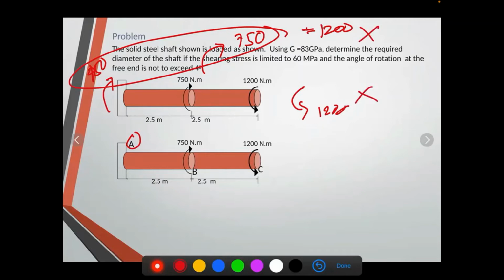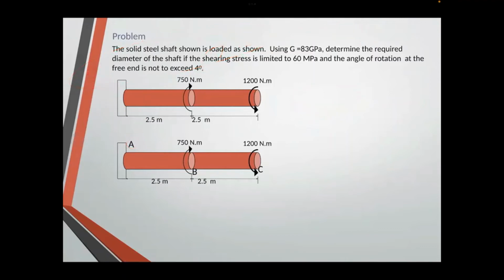So again, that's just a recap of your statics, computation of reaction. It's very important that you don't just solve, you should understand what you're doing. That's the concept behind computing your reactions: we just want everything to be equal if added. So 450 plus 750 is a clockwise rotation, and 1,200 is counterclockwise, so they will cancel each other out. So 0, no movement, so our structure is safe. Just in case you want to write it down, the reaction at A is 450.